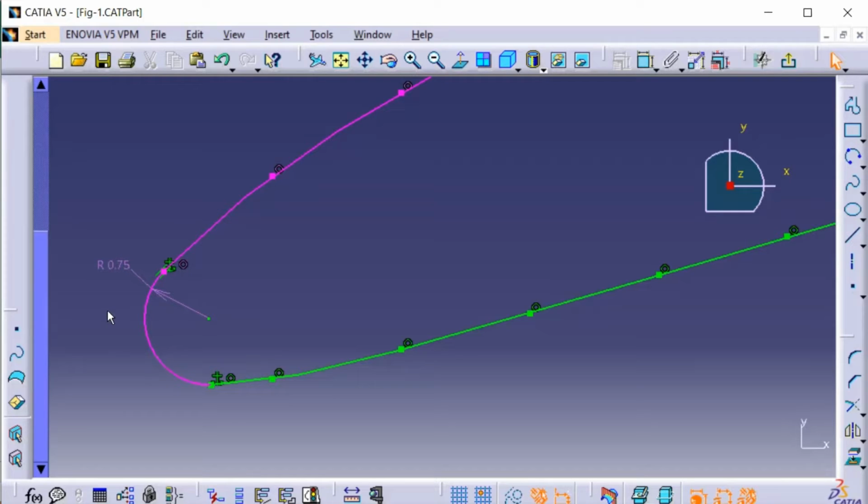So the aerofoil coordinates are exactly positioned to match the endpoints of the leading and trailing arcs. So while drawing the arcs, taking the endpoints, the perfect leading and trailing edges will be automatically developed. So if the designer chooses this method, we have absolutely no problems. But this is the ideal condition, which about 90% of the chances won't be the case.